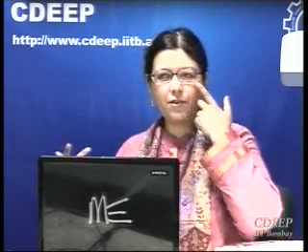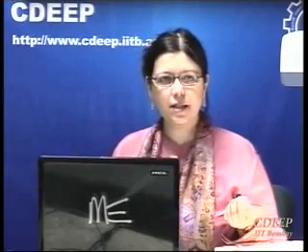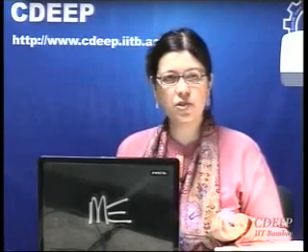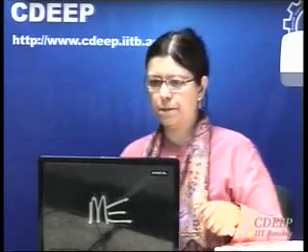This is the difference. If you look at abstract levels, concepts are easy to understand. Only the way they are implemented is challenging, because now you need a very good sample and sampling circuit at the input and then a very fast MUX at the output. Usually the input part is more challenging compared to the fast MUX, because a fast MUX can be implemented.